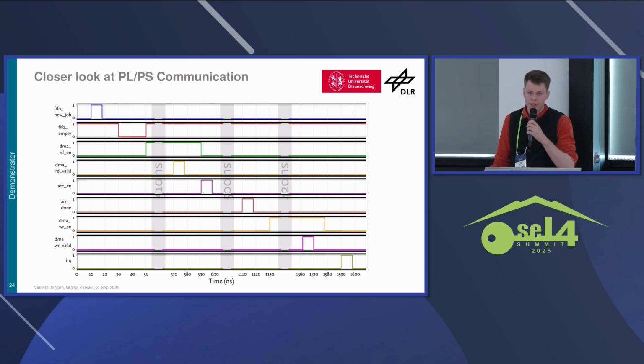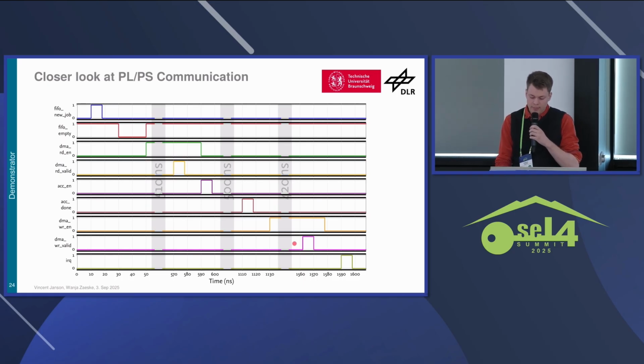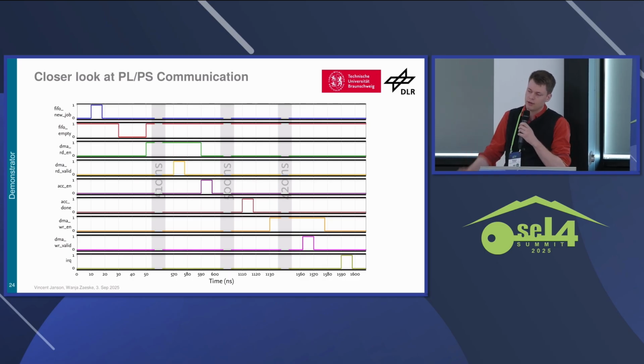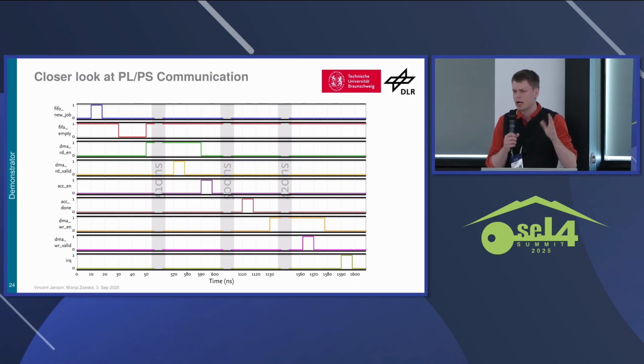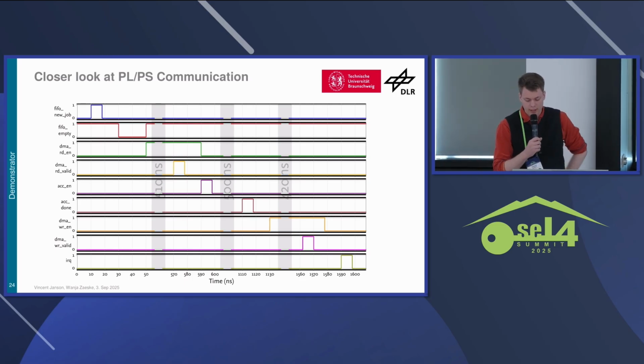That's just a counter that at 100 hertz counts from 0 to 50. And we can see that write back from the block RAM to the main memory of the PS side, again, is in the vicinity of 500 nanoseconds. So again, around 120 megabytes per second. So the DMA really is not performing as well as we would want.